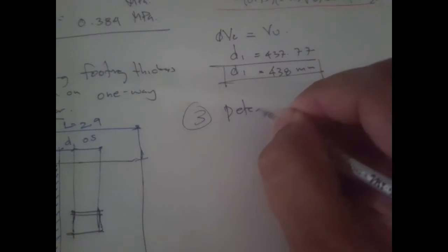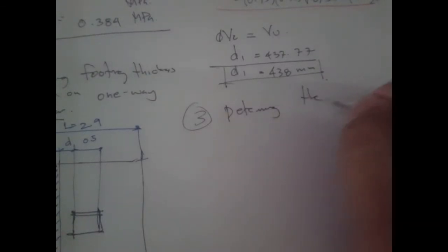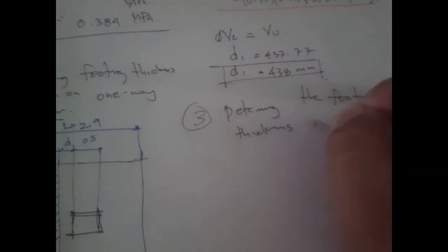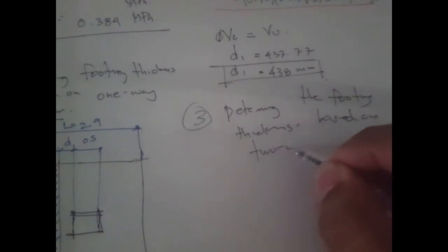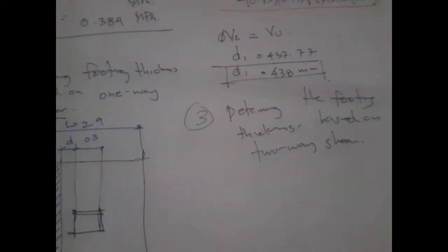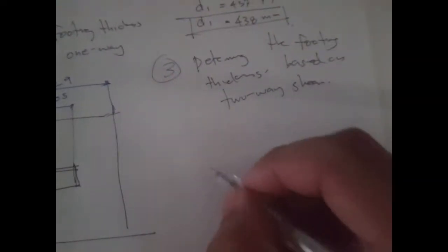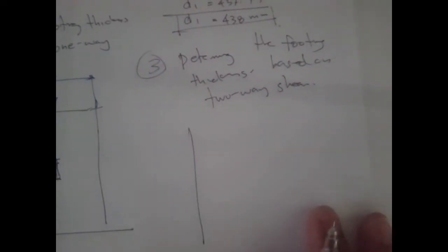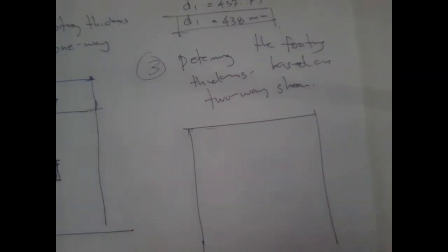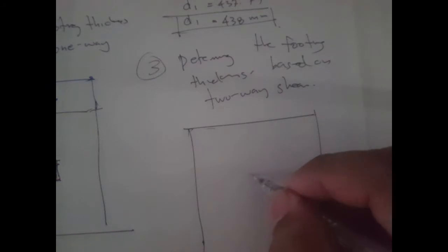So determining the footing thickness based on two-way shear. First is to draw the footing, let's say the footing plan.